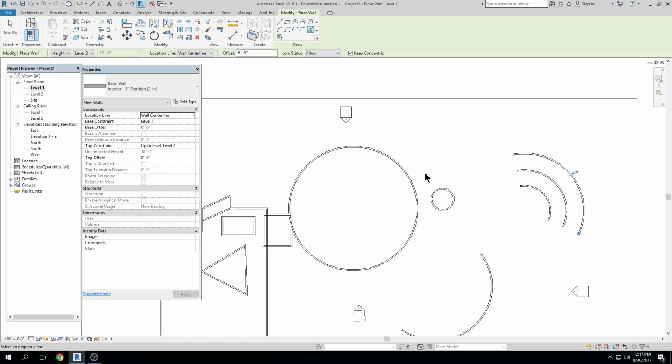You can use this pick option to very quickly start drawing over the top of your CAD drawing. Those of you that have worked in it know how valuable that probably is, to be able to just pick everything and start getting a really good drawing created very quickly from something you have in AutoCAD already generated. So pick lines will be very helpful for that.